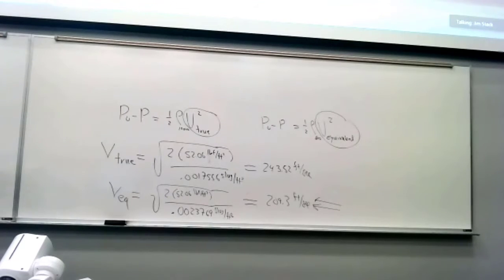Well, the equivalent airspeed is the calculated, indicated is what the dial actually shows. So the indicated is what you're actually seeing on the dial. The equivalent is if everything's working properly and your pitot-static tube is correct. And then there's calibrated airspeed, because typically what they'll do is they'll calibrate the airspeed on the airplane to account for the pitot-static tube and where it's located on the airplane, and how the flow goes into that tube actually when it's installed on the airplane.